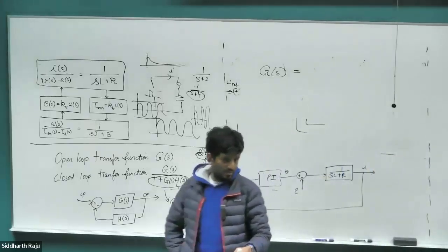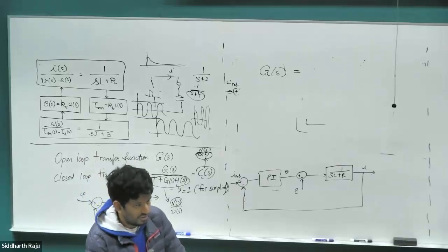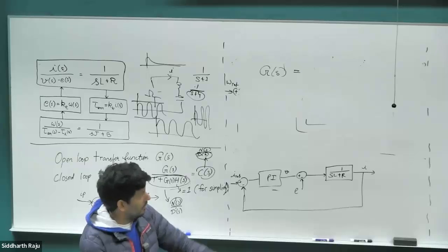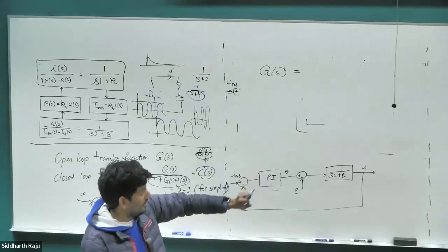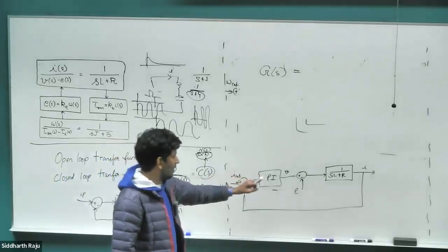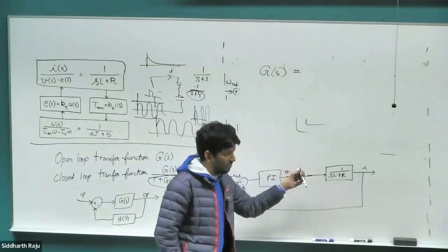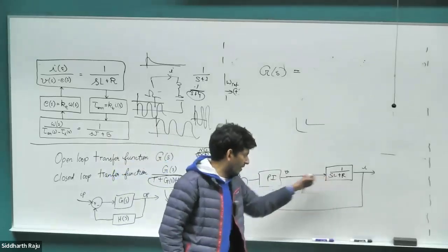Are we just assuming the mechanical system? Since the mechanical system has a higher time constant, we are only solving for the electrical system now. The mechanical system is completely out of the picture because you're only trying to control the current right now, right? And we said the EMF is no longer playing a role in this controller design because it's just a disturbance that's varying too slowly, so we can just ignore it. So the question is, what is this open loop transfer function for the system now?